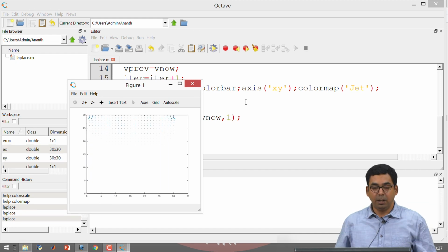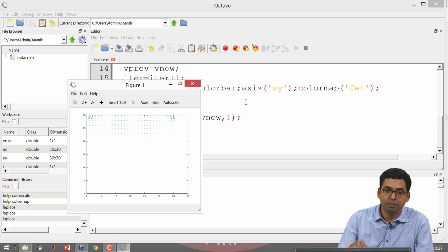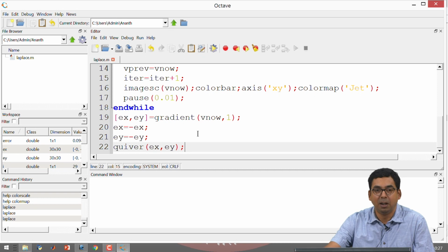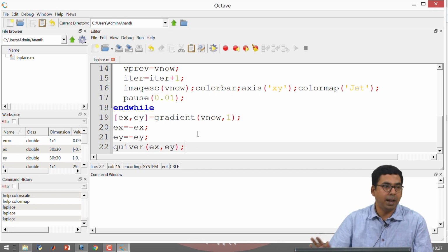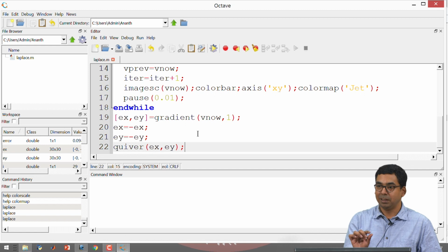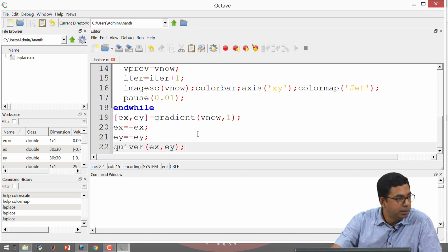Now, I notice that I am getting some arrow plots. It shows that the arrows are emanating from the top and it is doing something and it has become very, very tiny. I would like to have this plot on top of the voltage plot that we have calculated, and I would like to see really large arrows. The default setting is the size of the arrow tells you the magnitude of the electric field. I would like to play with all that to get a preliminary starting point.